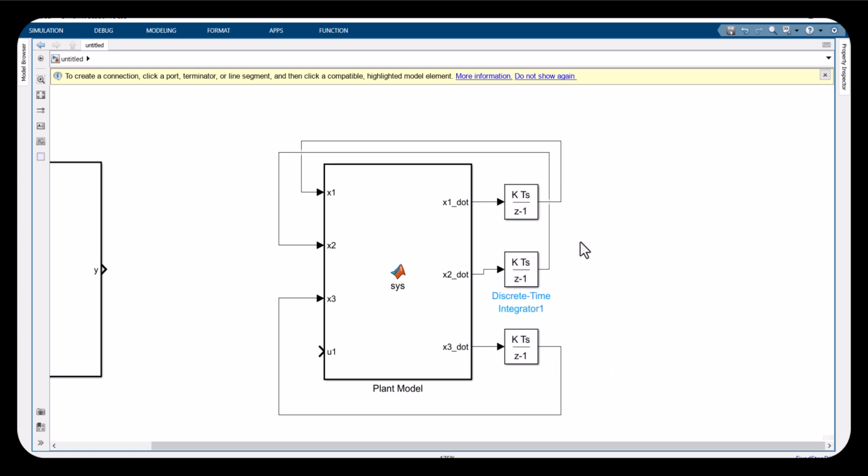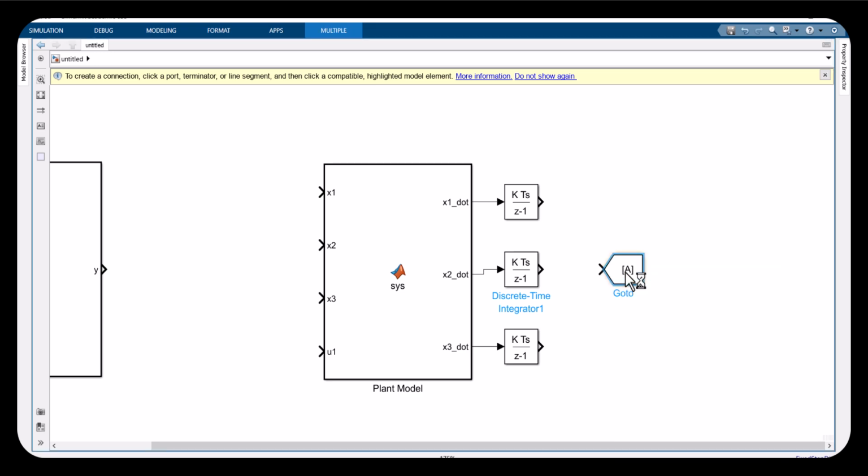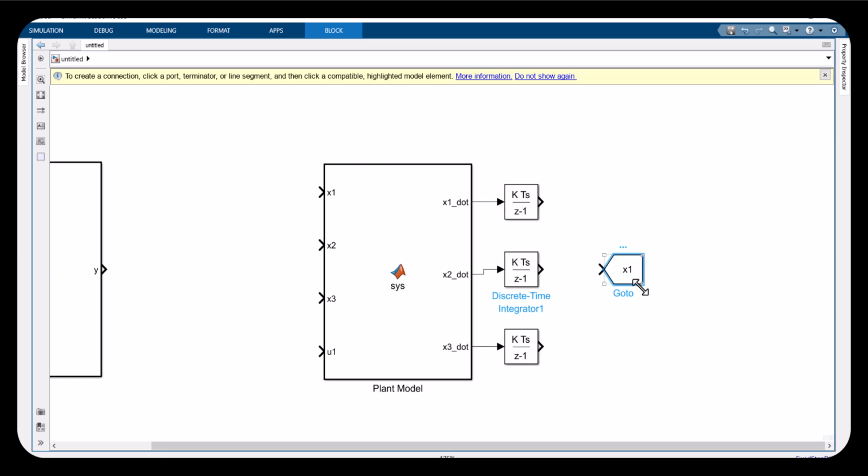There's a better way to avoid all these wires. Just type Goto. It is just like a transmitter signal. I always use this global variable because we'll make subsystems ultimately. So I can just make more copies. Each Goto block should have an individual, specific name.